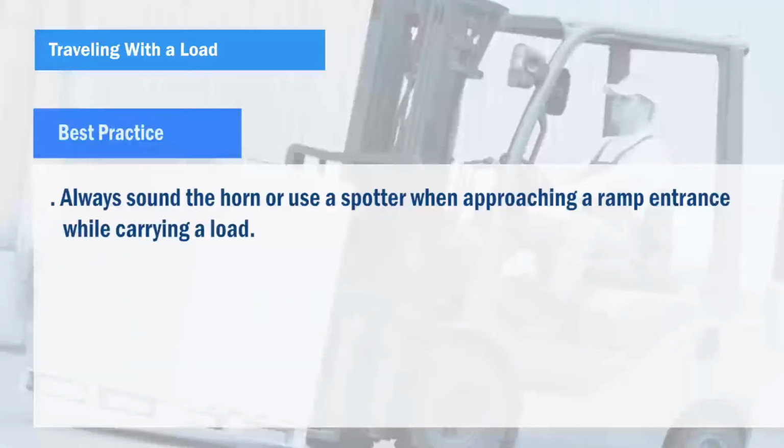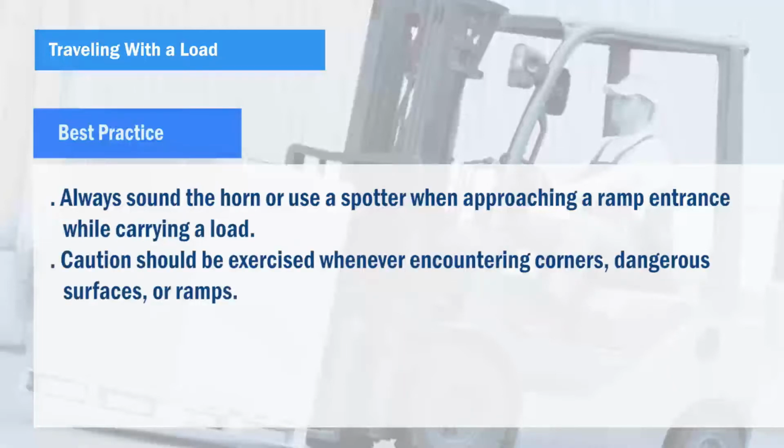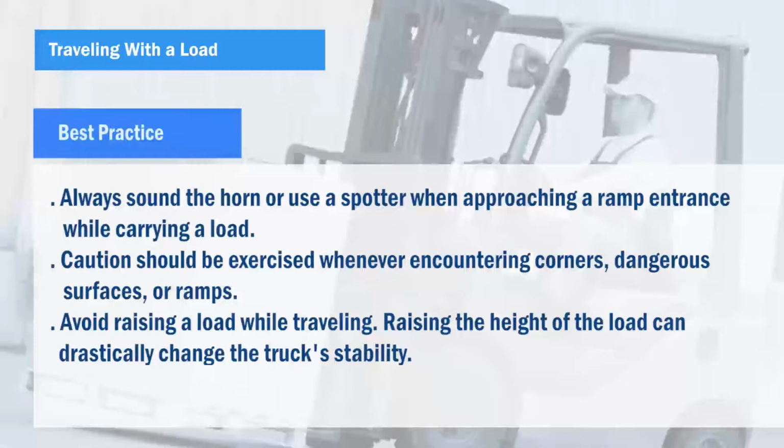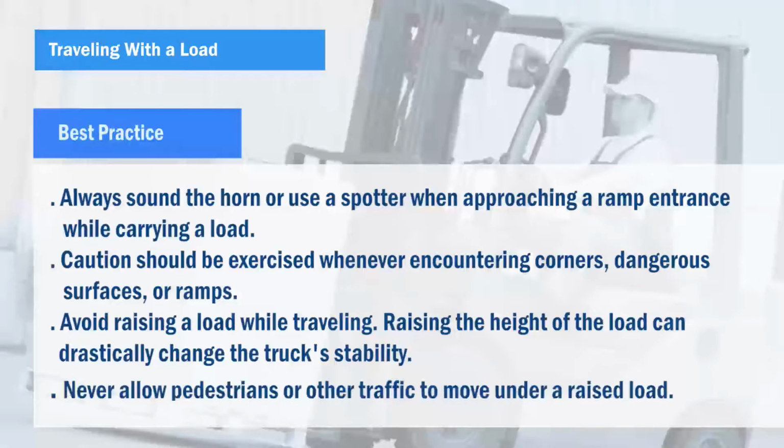Always sound the horn or use a spotter when approaching a ramp entrance while carrying a load. Caution should be exercised whenever encountering corners, dangerous surfaces, or ramps. Avoid raising a load while traveling. Raising the height of the load can drastically change the truck's stability. Never allow pedestrians or other traffic to move under a raised load.